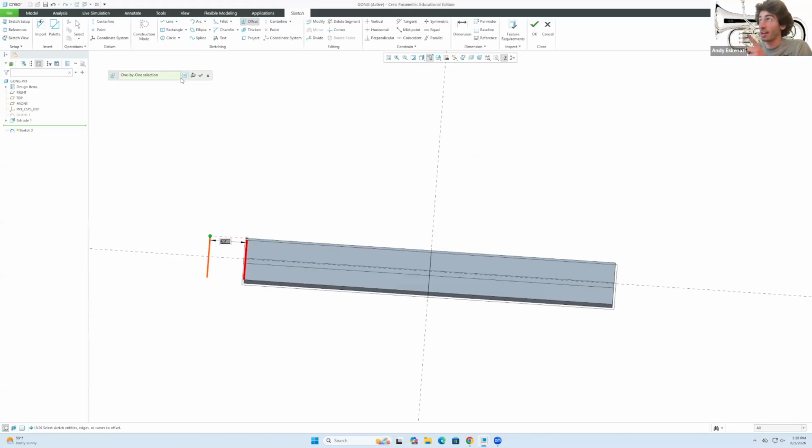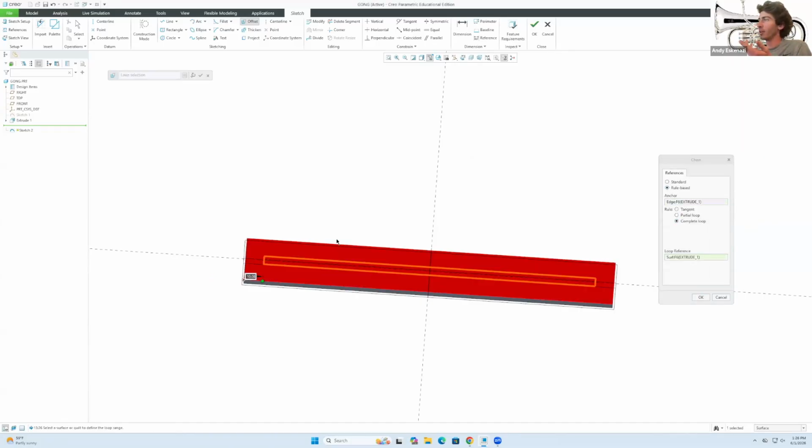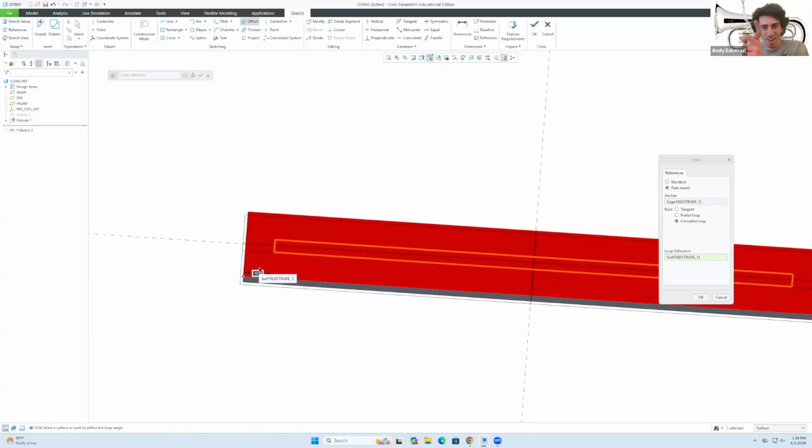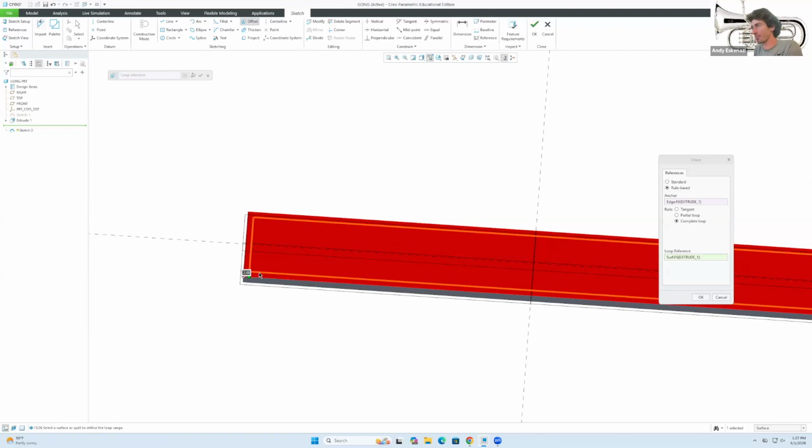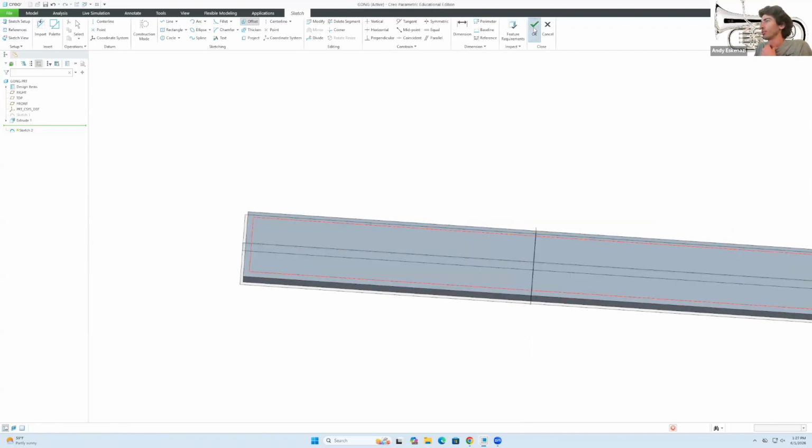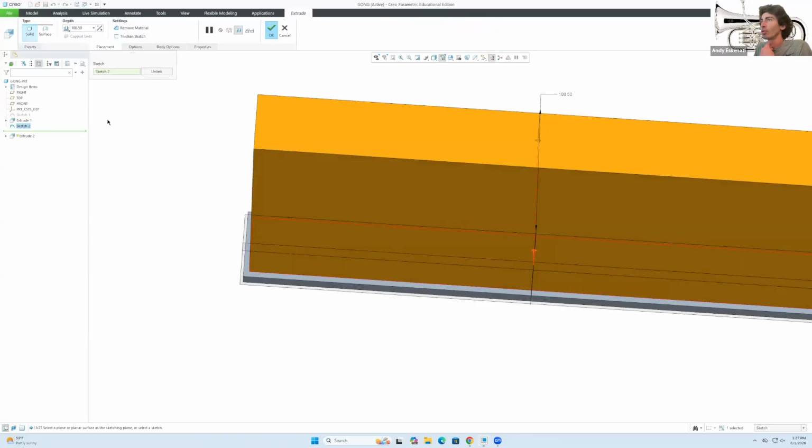What I think is fun is if I go here to this check mark in here, and I go to where it says rule based, and let's try full loop as an example, then it's going to create a little loop. It's like an offset of that rectangle inwards. So I can say, all right, actually make it offset by 2. I'll say okay, well, that's great, because now I'll do an extrusion of that one also by 5.